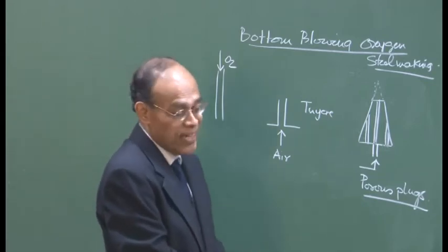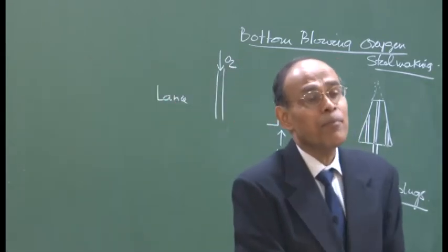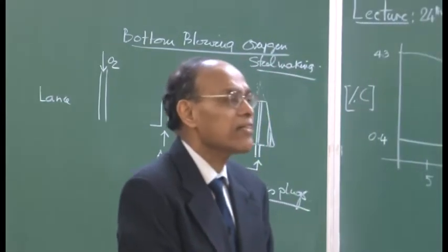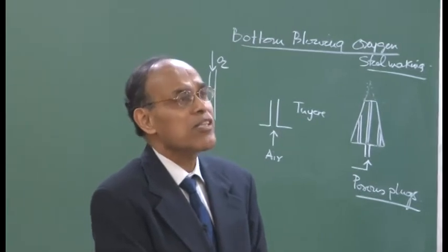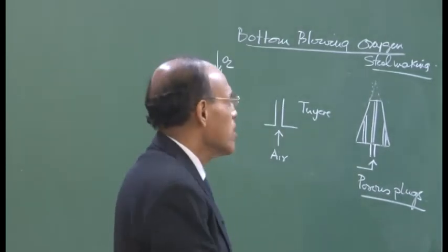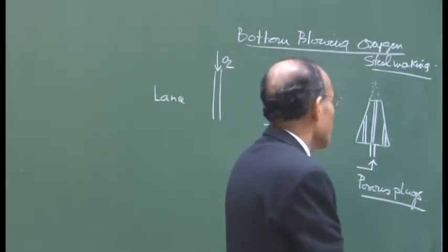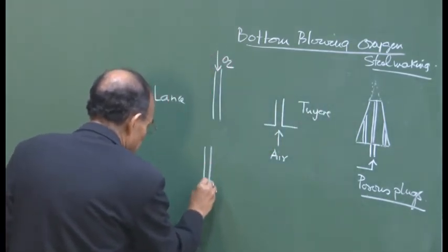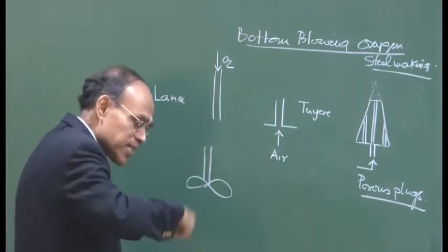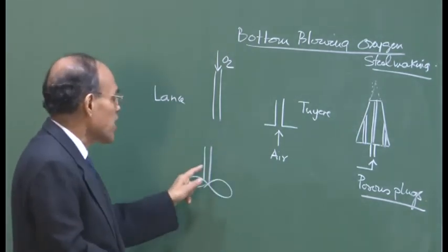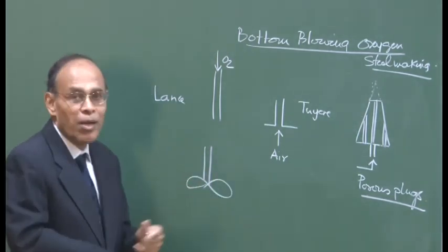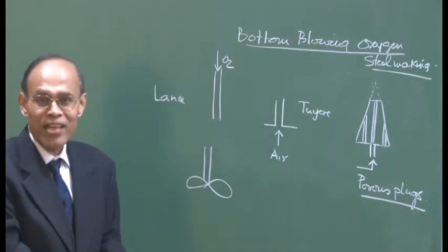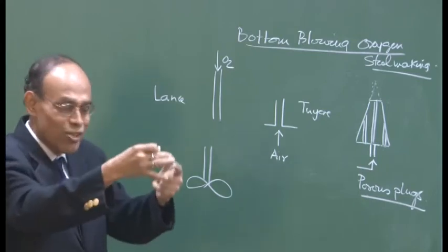And gas injection is important because most of the time we find the cost is cheaper. It is easy to maintain, and you can imagine putting a refractory propeller inside a steel bath and stirring it; the refractory itself will get eroded and contaminate the steel, particularly if you are talking of beyond primary steel making, beyond LD steel making, or the final stages of steel making.